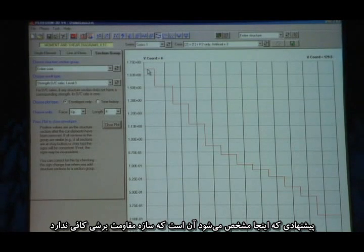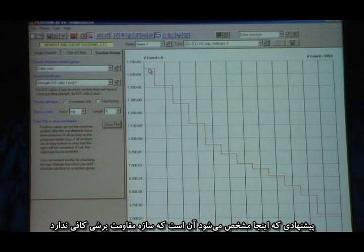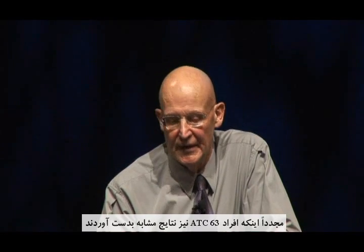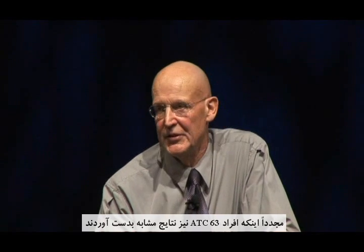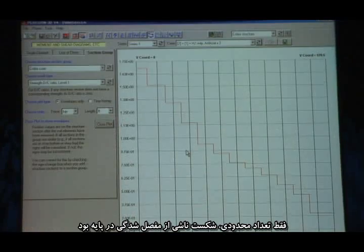The suggestion here, the indication here, is that this structure does not have sufficient shear strength, and it is likely to fail in shear at the base. And again, the ATC 63 people found a similar result. They ran a whole series of earthquakes, and they found that in a number of cases, the failure was hinging at the 6th floor. In a number of other cases, it was shear at the base. In a very few cases, only a very few cases, it was hinging at the base.